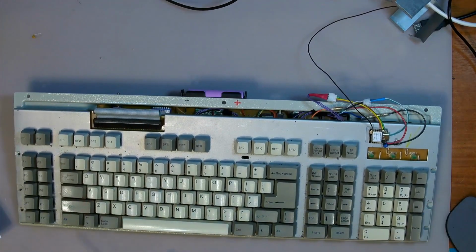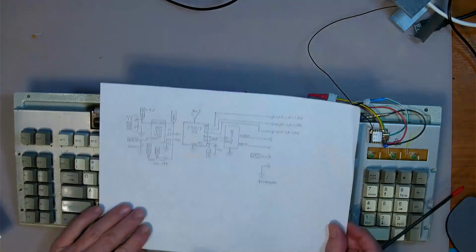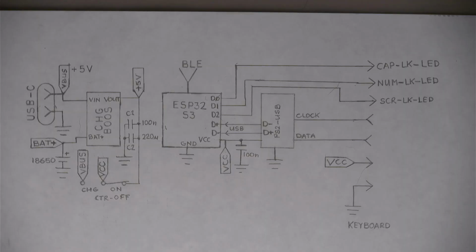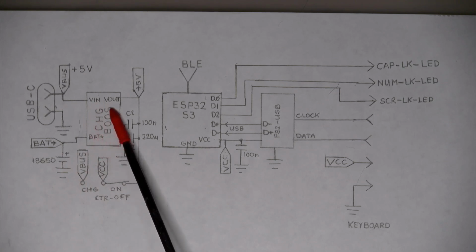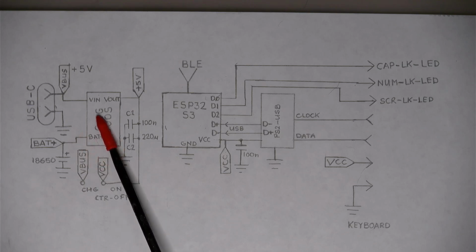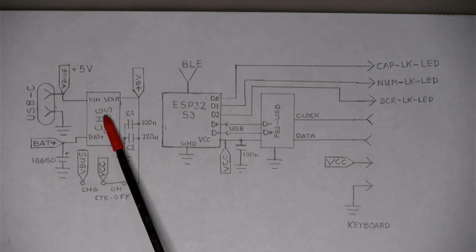And the actual circuit, let me zoom in on that a bit so you can see it better. All right, so this here is the circuit that we have, how we got it connected. At the center of it is a switch here, a single pole double throw center off position switch. You can see from that, this is a charge boost board. It has the battery permanently connected to it, and this little board has 2 LEDs on it, the green and the red. Green says it's fully charged and red is while it is charging.